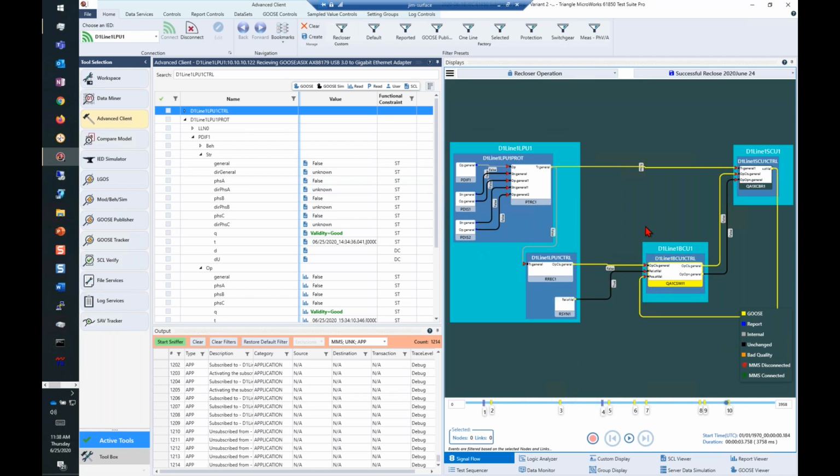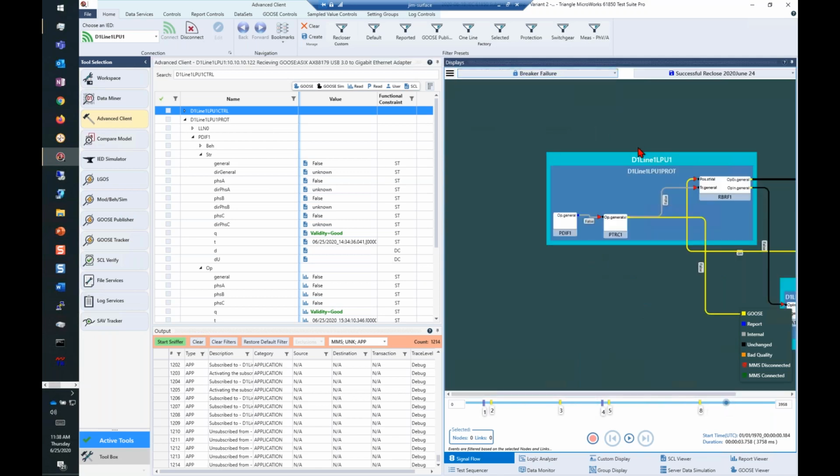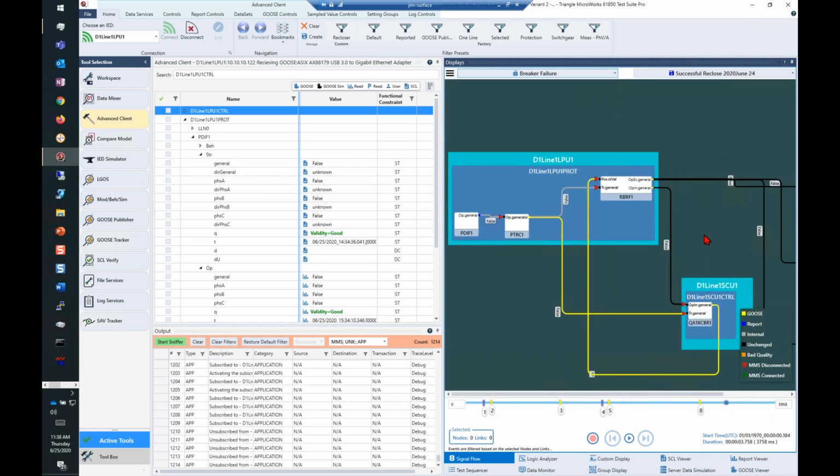What we'll probably do long-term is take the data that we came up with to create the simulation in DTM and then have different schemes that we can apply those to. So you only draw the recloser function here or the breaker failure function here and just isolate. So you don't have this big diagram that shows all of the GOOSE connections in the entire substation, because that can get overwhelming. You want to isolate it down to a list of specific functions that you're focusing on testing today.